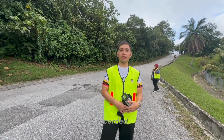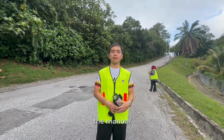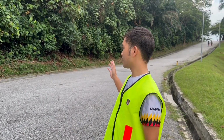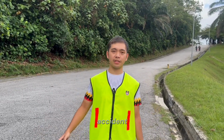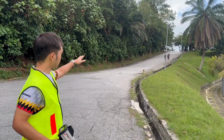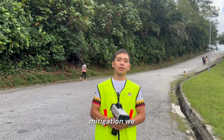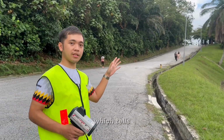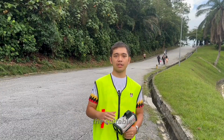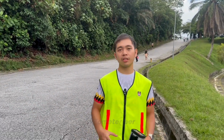When all the data has been recorded, we go straight to the analysis and get the conclusion, where we will compare the manual data and the equipment data. For this type of area, the risk that might happen is an accident. For example, during rainy days, the road user might slip from the slope and fall off the cliff. So as mitigation, we need to prepare road signage which tells the speed limit. From the research I have made, the suitable speed for this type of area, which is a slope, is around 20 km per hour.